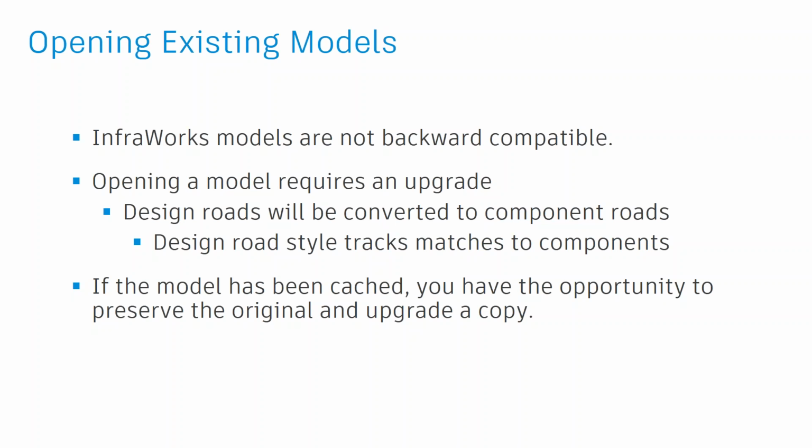If you open a model, you upgrade that model. So if you open the model in the latest release, you are upgrading it. It's not like Civil 3D, where you open a drawing and a message pops up that says this is open in an earlier release, and you can say okay, and close down that file without ever saving it, and it never gets upgraded. InfraWorks upgrades as it opens. Remember, there's no save command in InfraWorks. It's saving as you go. So as soon as you open that model, you've upgraded it.